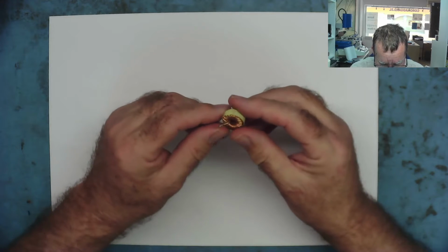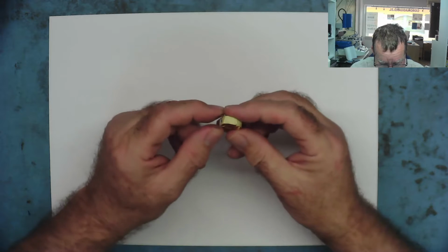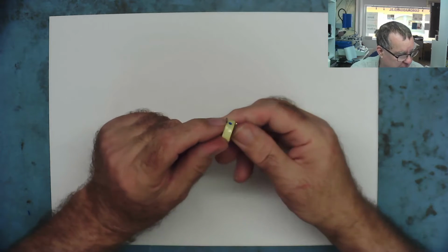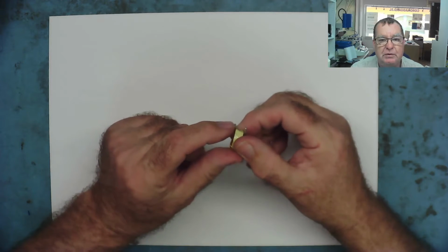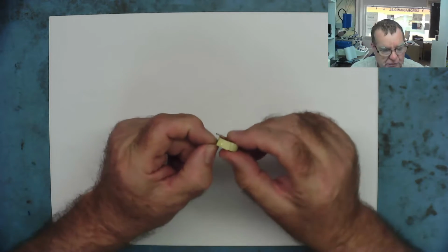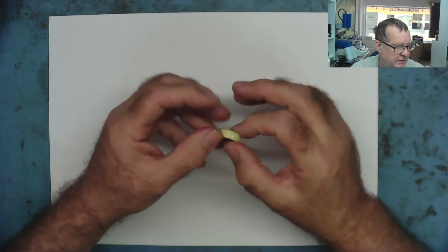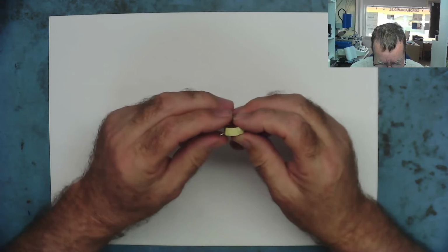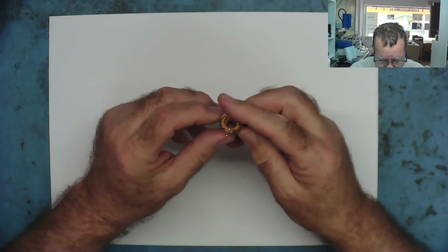The other thing that can go wrong with them is they could burn out or go open circuit. But to be quite honest, it's more likely for an inductor to go open circuit because where the leg is soldered to the board, the solder joint has gone because of the weight of the component sort of waggling around over the years, especially if it's an item subjected to vibration, you know, something that's portable, for example. So really that's two ways they can fail.